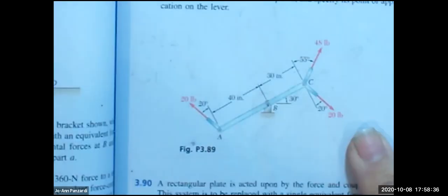Right. And then I saw your solution: you calculate the y component of force A and add it with the y component of force C. I thought you mentioned that as a couple, the force on point A cancels the negative y component of the force pointing down at C. Okay, so the resultant force on this problem, the 20 and the 20 cancel. So the only resultant force on the system is the 48 pounds up to the right. So I could take the 48 and get the x component and the y component so I could represent it in vector form. You're good with that? Okay, now for the moment is what your question is?